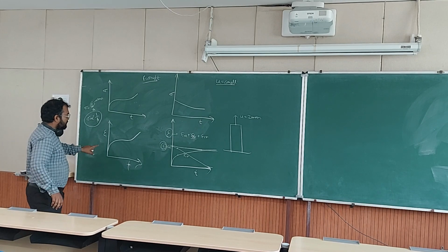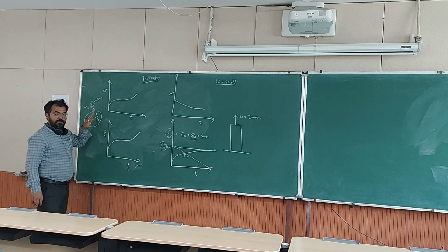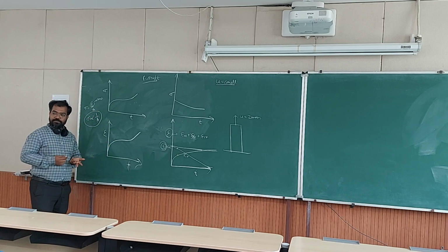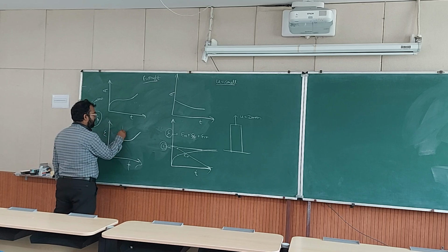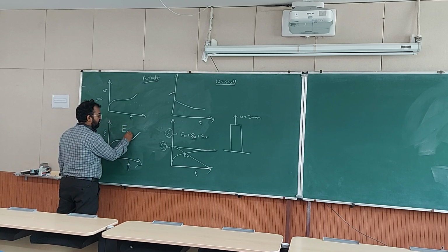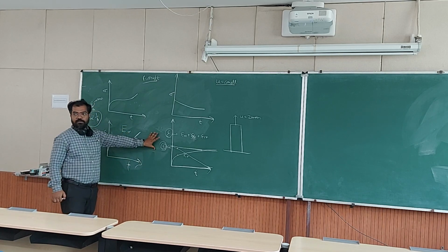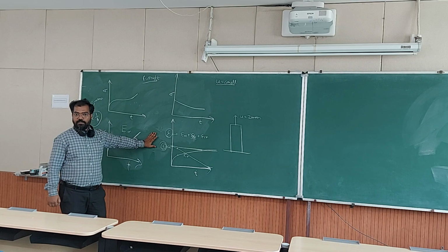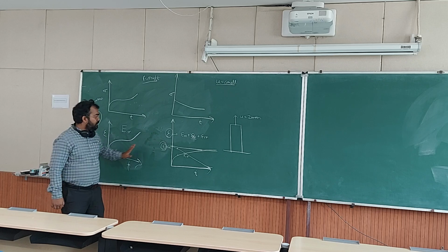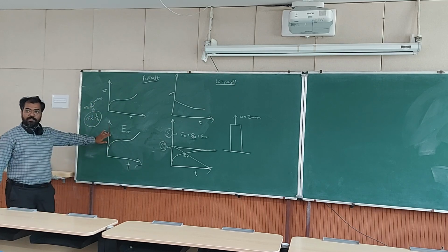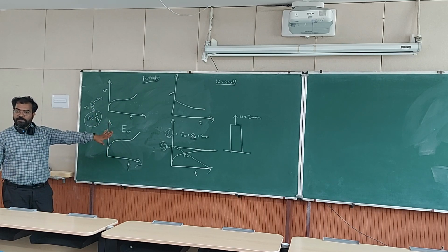So in this case, the modulus which you get between stress and strain is called creep modulus. Okay? And in this case, what you get as a modulus between stress and strain is called relaxation modulus. So in this case, strain is a function of time, and in that case, stress is a function of time.